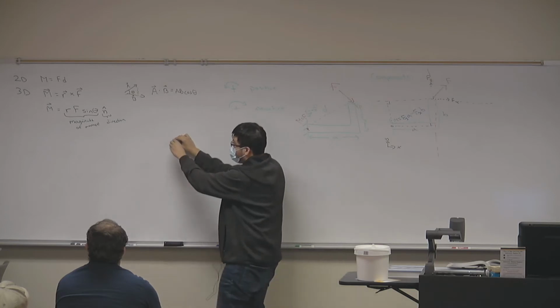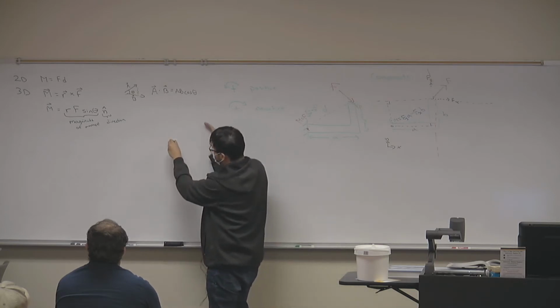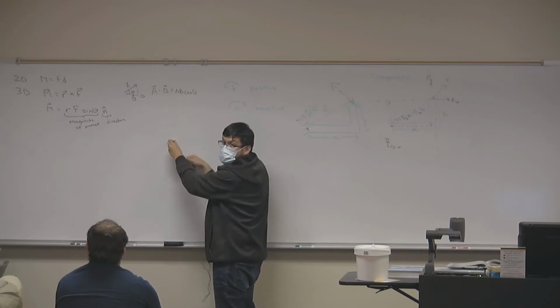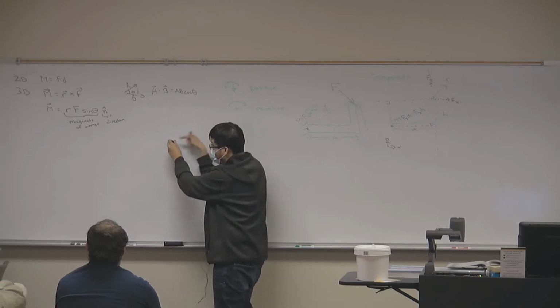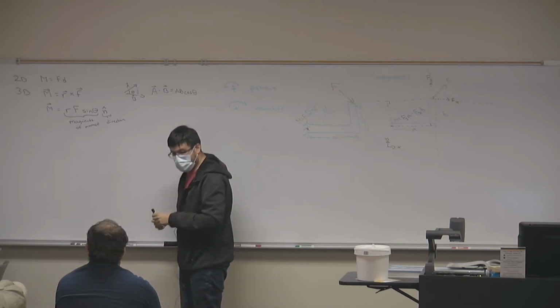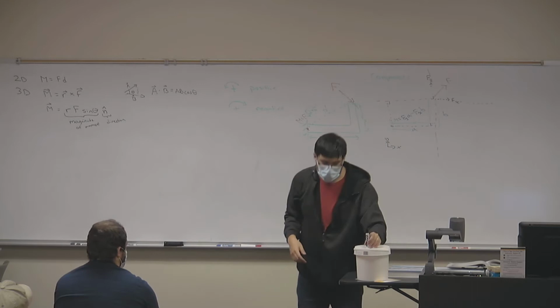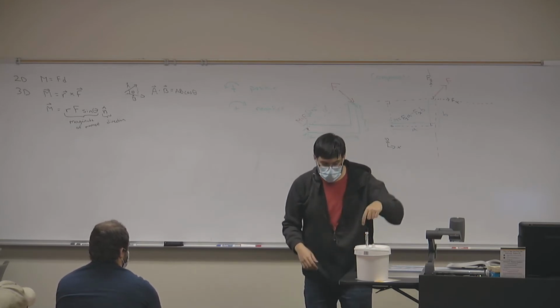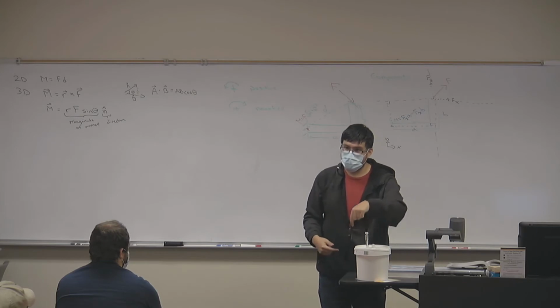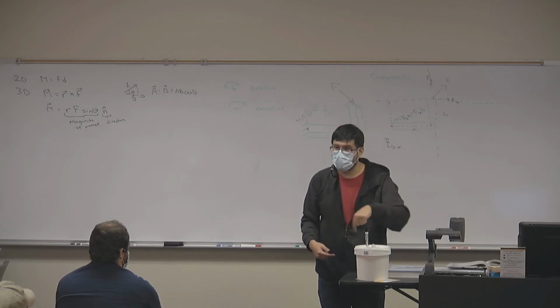If my rotation is counterclockwise to this vector, then it's a positive moment. If it's clockwise to this vector, it's a negative moment. Likewise, if my n is here, same thing. If it's counterclockwise to this vector, it's a positive moment. If my rotation is clockwise to this vector, it's a negative moment.